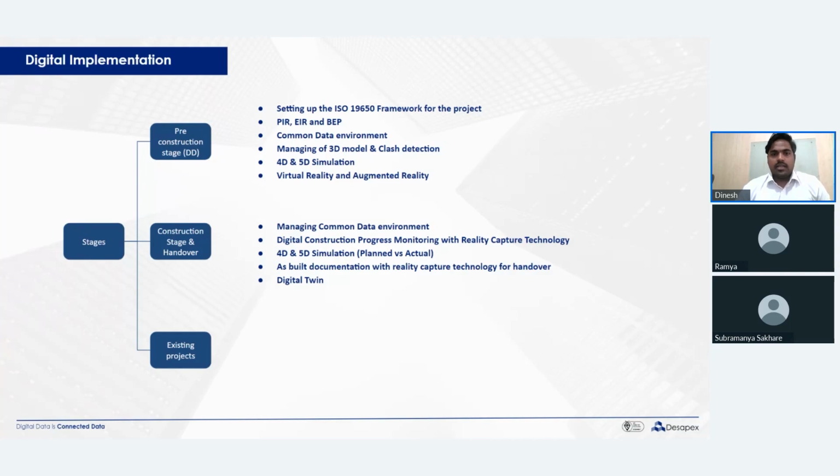And then at the end of the project, it's very important to capture everything that has been executed back to the model. Many might agree and some might not, but a lot of people change the GFC drawings to as-built and submit. A lot of the changes that happen on site generally don't get back to the models.